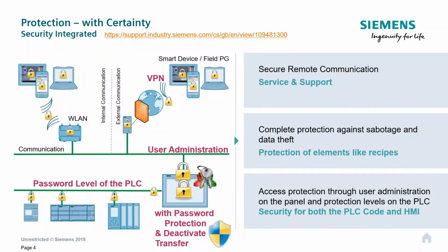Which is then really great because we can also group these together and allow certain employees access to certain machines, maybe machines that they've been trained on, for example, and also control the levels of what they can actually do on that machine, whether it's operate, engineering, maintenance, all those sorts of tasks. This is also very important to make sure we lock down this display and the users, especially if we are going to connect it to higher level systems or remote systems.